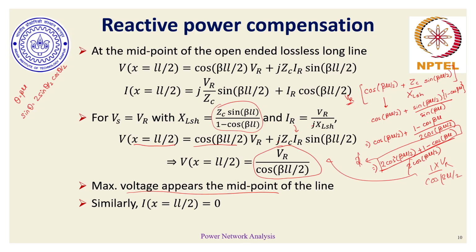The line parameters are distributed. Line capacitance is generating more reactive power than the line inductance. So more reactive power has now accumulated at the receiving end and at the midpoint of the line, and hence the voltage profile has gone up there. So by compensation, we can maintain the receiving and sending end voltages, but there could be other drawbacks or demerits. That's the overall intent and summary behind this discussion.